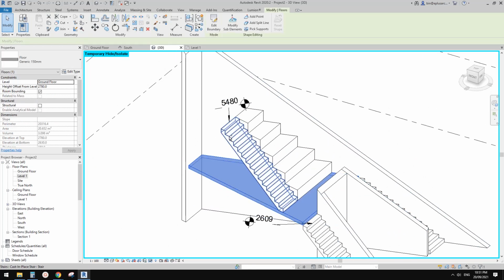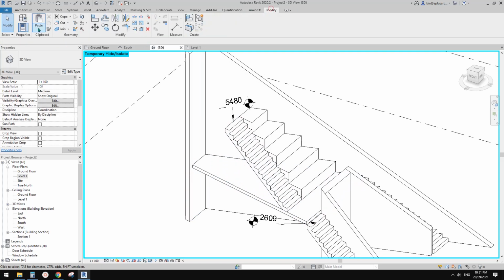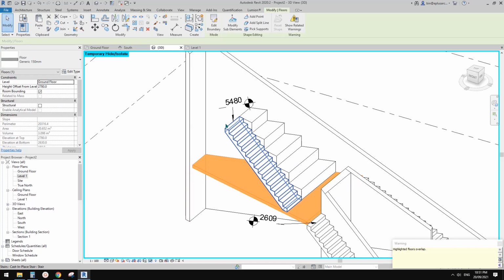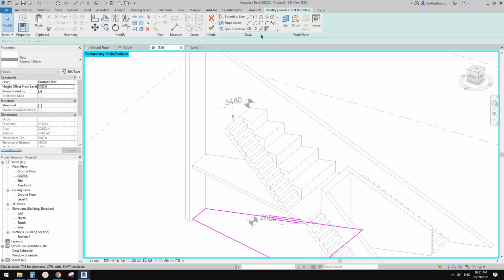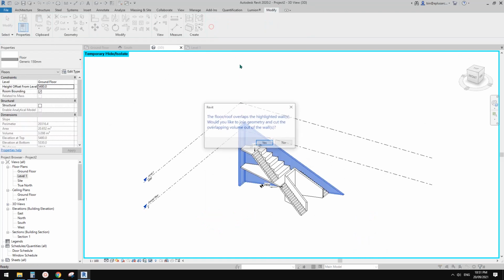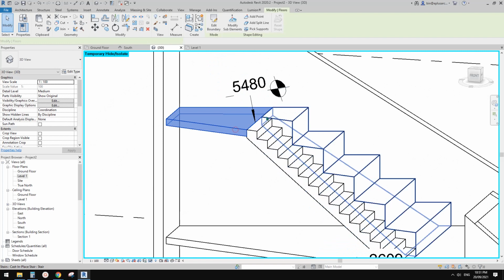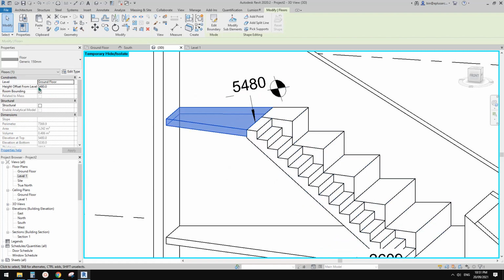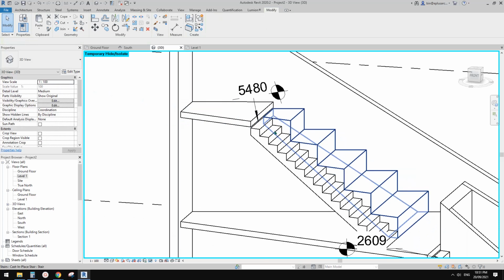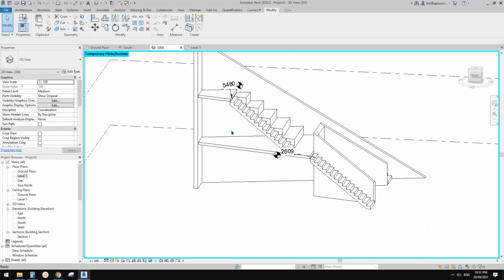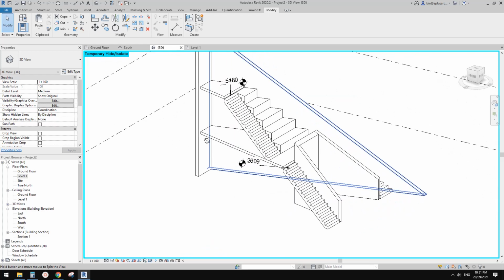So that's it. Okay, so now we can create another floor here. So what we can do is Control C. Sometimes I'll just create a new one and then lift it up 5480 and then edit boundary and maybe pick this line, trim, and that's it. Okay, so then that's it. If you want to, you probably need to increase one level or just equals plus 170 or 180. So I'll just use 180. Yeah, something like that.